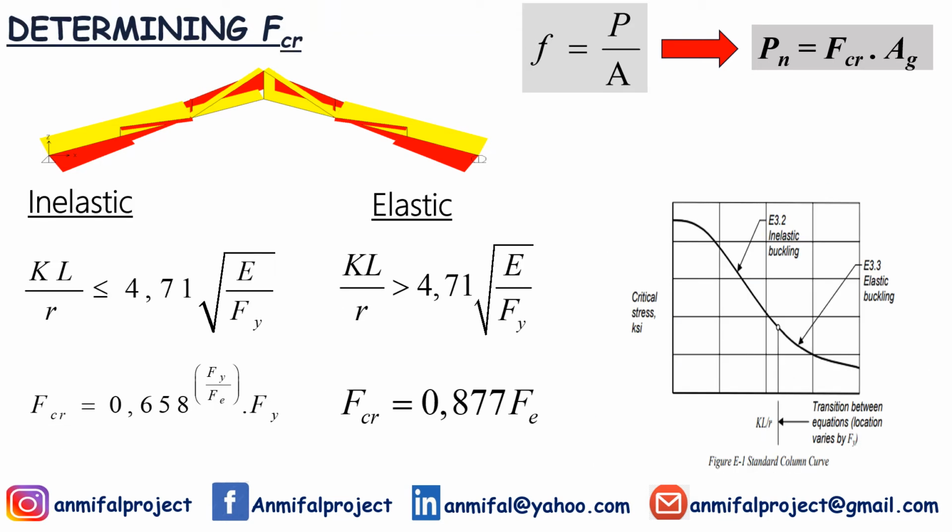Now we have the question of how to determine the critical stress. The critical stress can be determined by distinguishing between inelastic and elastic compression members. How can you identify them? When the slenderness ratio KL/r is less than 4.71 times the square root of the modulus of elasticity over the yielding stress, the critical stress can be computed by 0.658 to the power of the yielding stress over the Euler stress. Then we multiply it by the yielding stress.